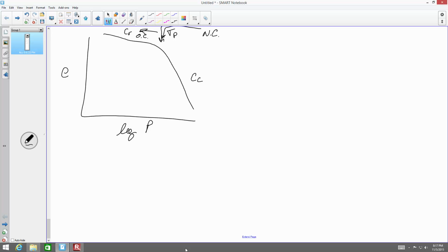So let's work through these. Let's look at D first. It appears to have been subject to a greater loading condition. It would be over-consolidated, right? So right now it's the same as what we see, so it's not D. Let's look at B. It appears to have been subject to previous desiccation or drying. That causes over-consolidation, so it's not B.